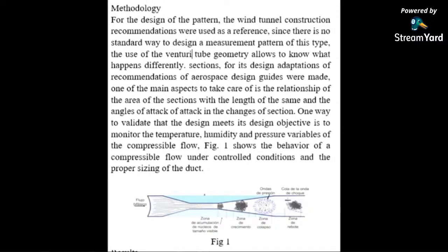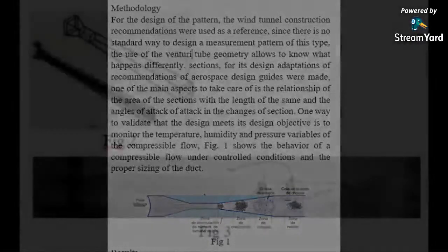For the design of the venturi arrangement, it is necessary to consider several factors that allow for adequate section changes. The design of this venturi duct corresponds to a subsonic speed region, which allows us to cover a large number of circumstances in which measurement can be made using the PIV technique.